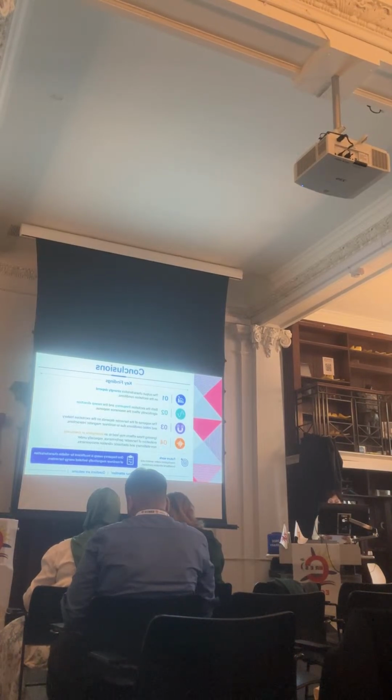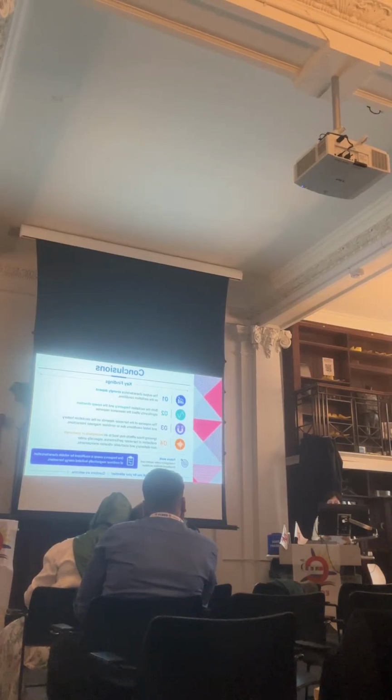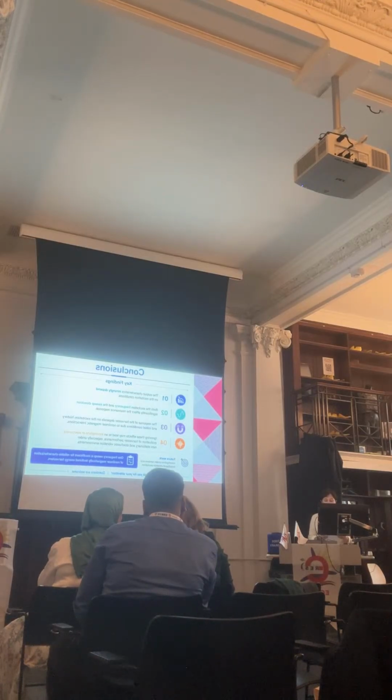The results also indicated that the system response depends on the excitation history and the initial conditions due to its non-linear magnetic interactions. Therefore, these effects should be taken into account when evaluating the performance of magnetically levitated energy harvesters, especially for applications involving variable and stochastic vibration environments. That's all.